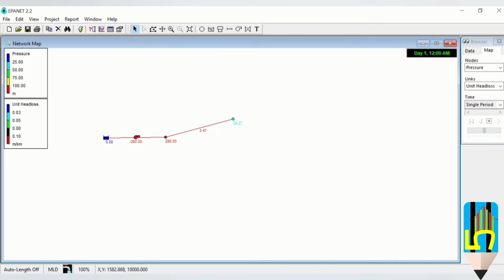But remember this, the pump definitions and the pipe sizes will be taken from the standard readily available material that is available in the market, right? Again, since we have increased the pipe dia the unit head loss is okay, but let's check whether there is a change in the velocity and if that change is within the permissible limits.